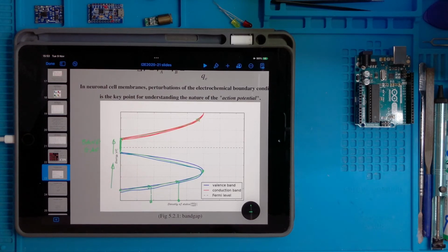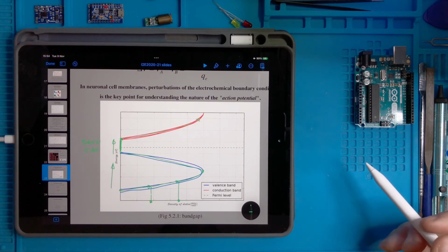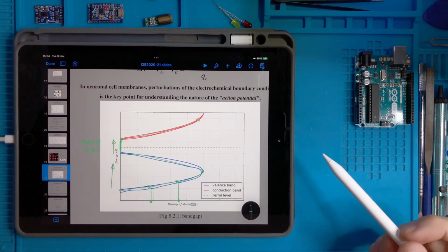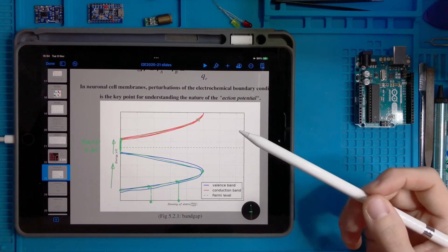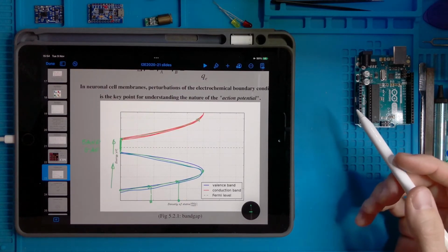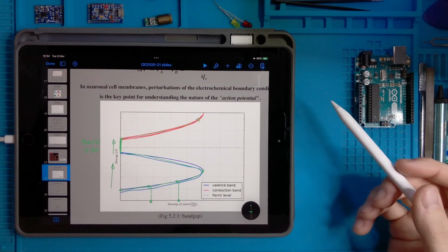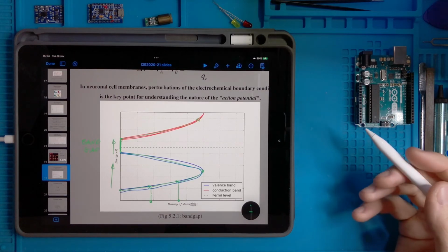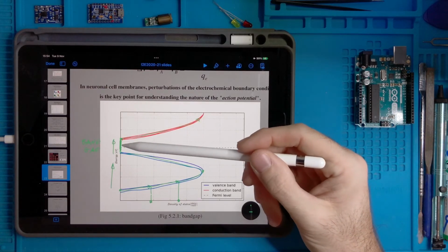But in this case, what happens is that for the insulators, the electrons would have so much energy that they will create a lot of scattering, they will hit the ions of the atom, and probably they will destroy the material. Basically, this is a so-called electric discharge in the material. Then the material changes, and then it's not very useful. And it's difficult to have this condition in an insulator, especially if it is a good insulator with a very high band gap.